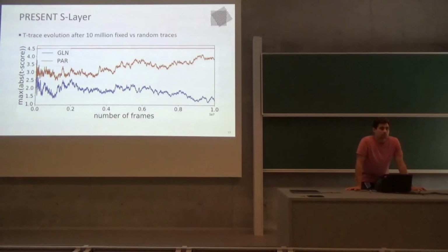But it's noise free, it should jump on anything. No, it depends on your extraction model. How does parasitic extraction work? Parasitic extraction can give you very precise coupling between neighbors, but if the parasitic model is very rough, I don't know which tool you use, it just gives you capacitance to ground, and that's it, right? But that's out of his control. That's what these EDA tools are. Yeah, but it's important to understand the limitations, or how much I rely on the accuracy of the tools.